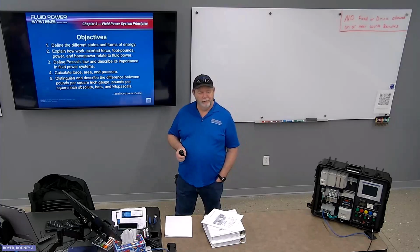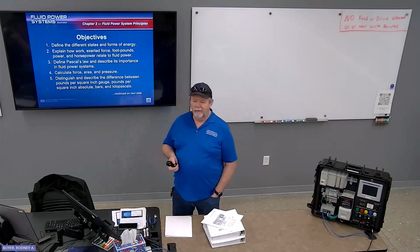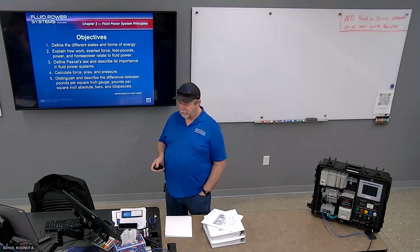Atmospheric pressure. What's that mean? At sea level, pounds per square inch absolute has 14.7 pounds added to the gauge. Whatever gauge pressure is, plus atmosphere. And like Will said, at sea level it's gauge plus 14.7 pounds.